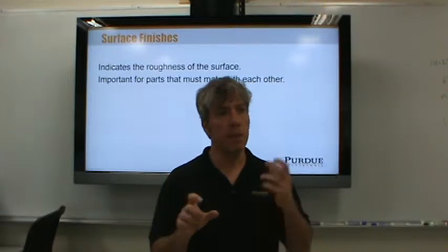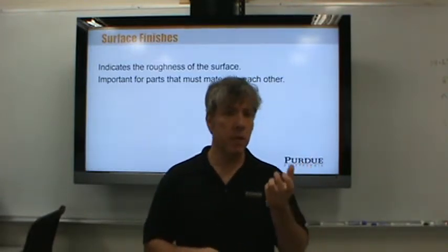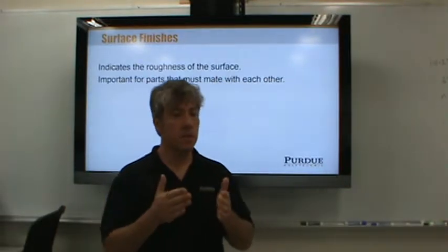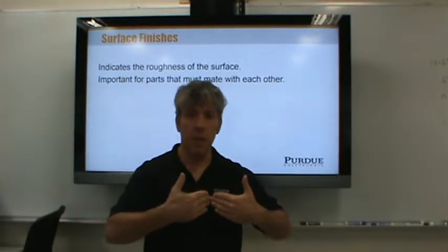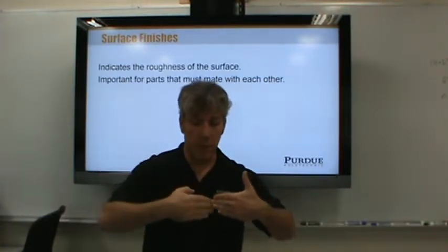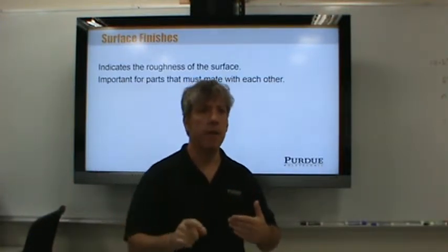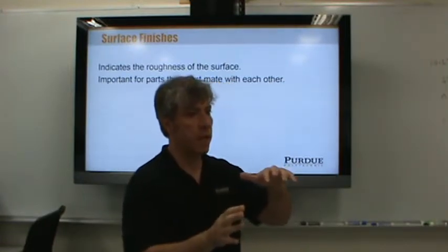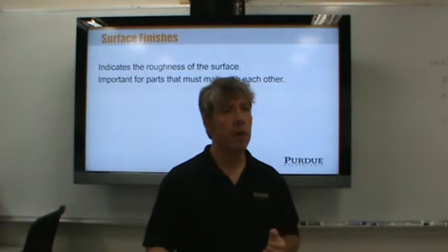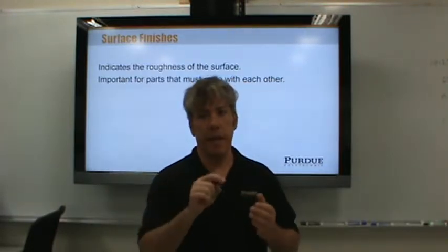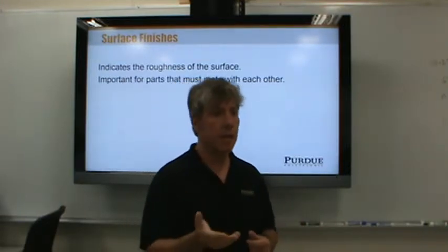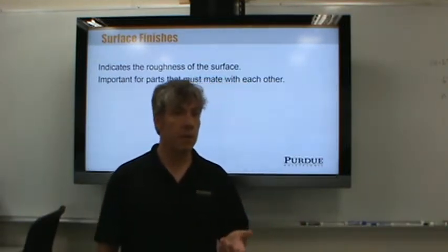That could be a lot sloppier than the lens. The lens, especially the optics in the lens, had to be much more precise because the lenses actually had cube features in it so that light coming in would bounce off one angled surface, bounce off the other angled surface, and come back out. That way, if the truck's off to the side of the road and has no power for whatever reason, because of some failure, an oncoming car's headlamps would actually shine light into the reflector and back to the driver so the driver could see the truck, even though the light was not on.